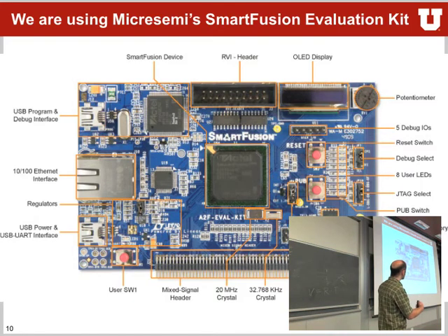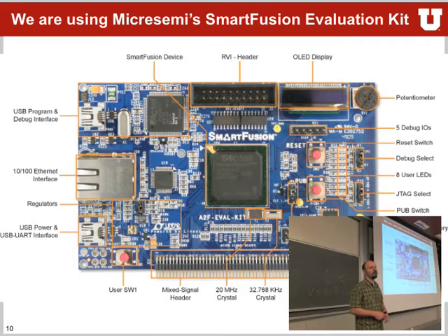On the bottom side, there is an SDRAM. It has an OLED display. It has a little potentiometer. Down here, it has an interface where we actually have an adapter board, a red one that plugs on the side into it. Be careful with these little pins here. They are very fine, and you can misalign the attachment board, so try to push them together properly so that they actually hold. You have a couple of push buttons and a couple more pins for different switches and stuff like that. So in lab number 1, you actually will use these pins up here, not the big board on the bottom, but in later labs we will use the bigger board for more interfacing, more I/O capabilities.